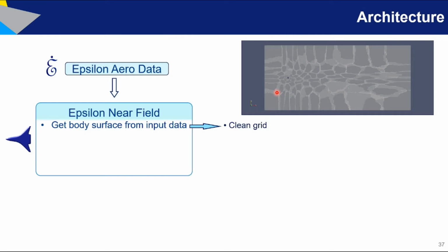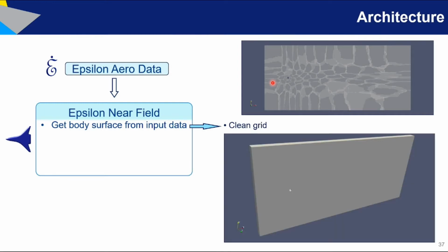But the problem of doing that is that when you load the final converged simulation into ParaView, ParaView will recognize these interfaces separating each domain and will generate a sort of weird unphysical faces. These are actually surfaces inside ParaView. And we have to get rid of that, and I will show you how we achieve that.